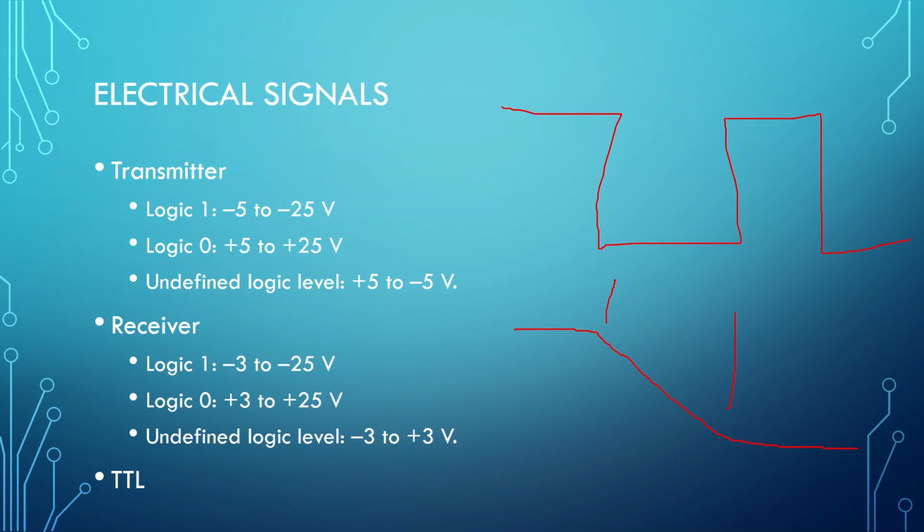If you're starting to get into the new world of microcontrollers, like the ESPs, those are only 3 volt devices. So when you're trying to do a serial communication with it, it's only a 3 volt signal, not a 5 volt signal. And if you're trying to do something right in front of your CPU to CPU, like on board, it's only 1.2 volts. So our voltages kind of keep coming down over time. Originally, I was really annoyed by the whole different voltage thing, but it's just something you've got to deal with.